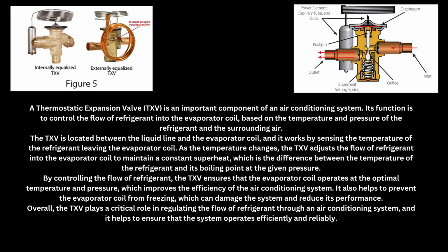So, just an overall breakdown, all systems today have thermal expansion valves on them. Refrigeration systems have thermal expansion valves on them, especially walk-in coolers and freezers. Now, the ones for the home, it makes it more reliable, more efficient, can absorb more heat load. It can transfer more refrigerant when needed by leveling the spring and adjusting the spring in the needle and seat in the orifice. It can adjust, either giving more or less depending on the heat load inside the home.